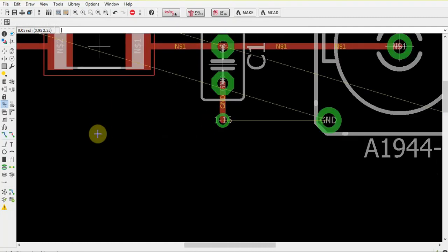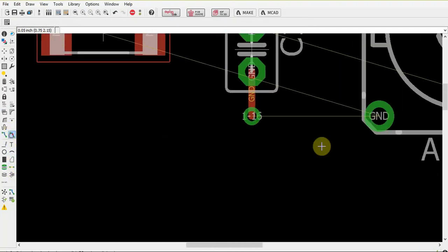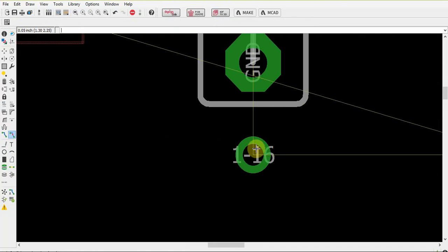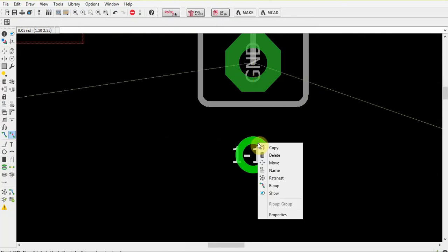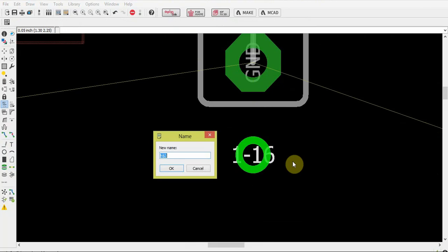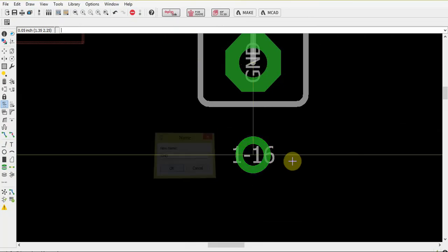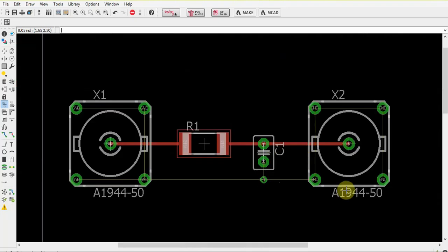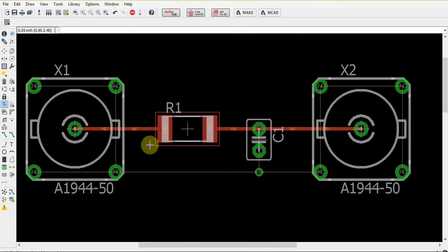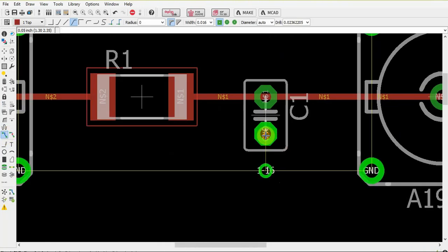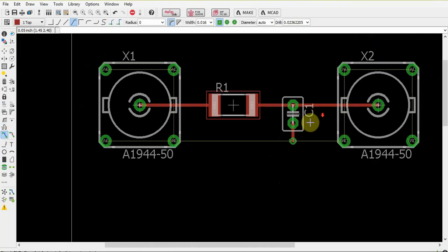Oops. So that's a bit of an issue right now. We can obviously correct that by just doing rip up. Rip up is the opposite of routing. You can tear apart. Exactly. We'll just keep that like so. Now this one has to be named so that this connects to ground as well. This has just been given an arbitrary name. We'll have to change that to GND. Now you can see all this goes to ground. Now we know where to go. So that's very simple, like so.